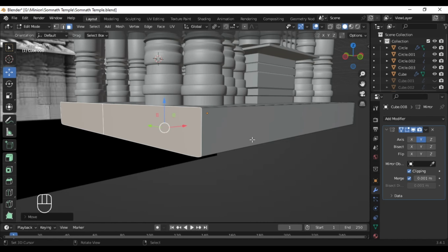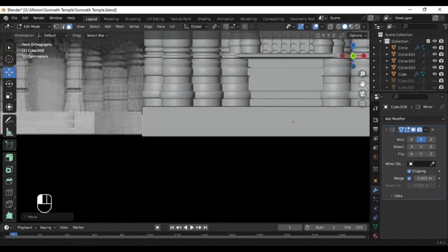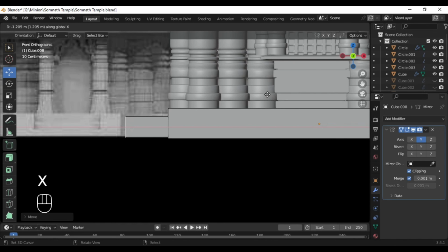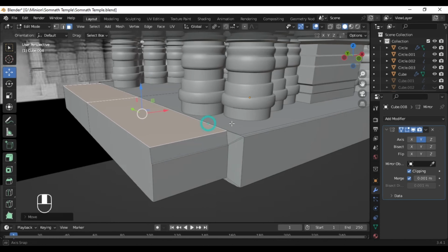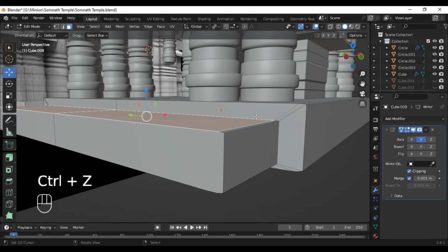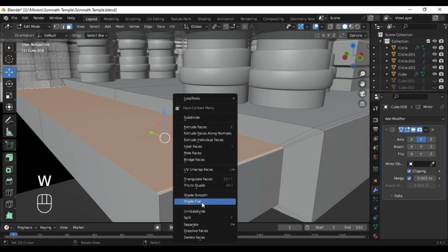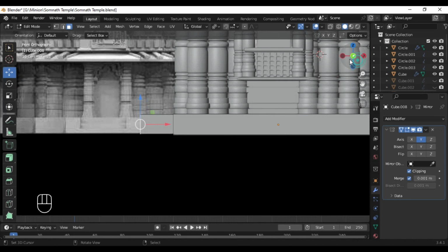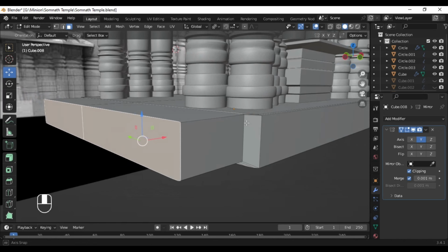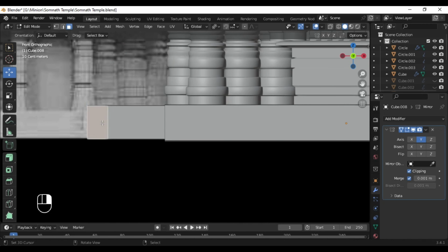And on the other hand side we can do the same process. First of all insert a face and then extrude it along the x-axis.